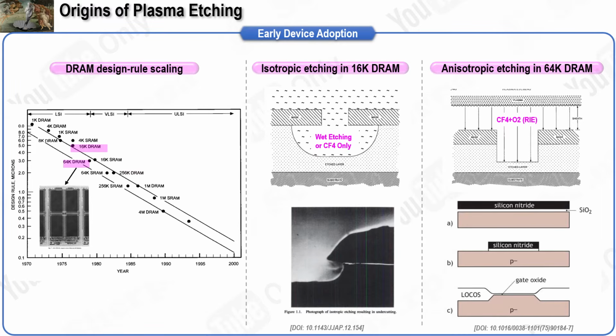In the production flow of that time, the silicon nitride barrier used for LOCOS isolation was removed by hot phosphoric acid and related mixtures after a short hydrofluoric pre-clean. These liquids often showed an incubation delay before etching, they attacked common photoresists, and they produced isotropic profiles that undercut the mask and loosened critical dimension control. Plasma solved those two pain points: resist damage and timing control.